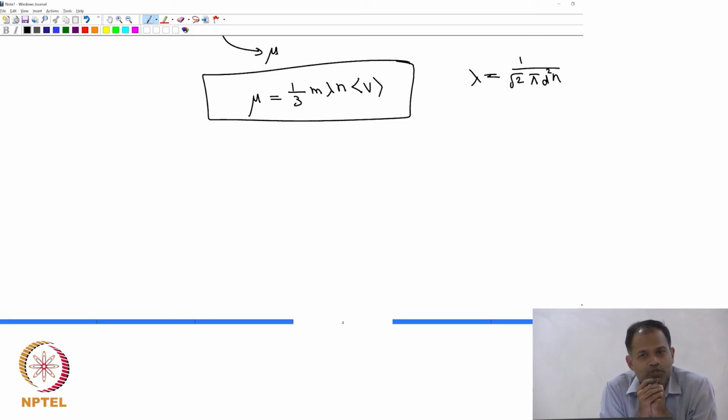For most liquids, when you increase the temperature, things become loose and viscosity goes down, but the viscosity of a gas actually increases with temperature. That is important, because many times in factories you would want to heat a gas and do things, and increasing the temperature is only going to increase the viscosity of gases, not decrease it, but for liquids it is the other way. That also means that the derivation we have done is not really true for liquids.